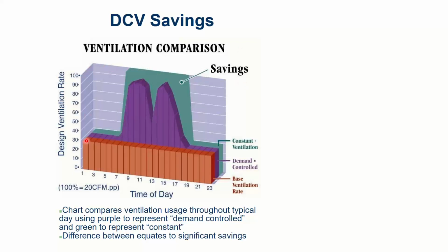But in the unoccupied hours, the damper goes open when I turn the heating and cooling on, and then all the way closed, and then open, closed, open, closed. And for this building, it averaged out to like 29% or something. So instead of showing this sawtooth pattern on the graph, they kind of just averaged it right here. In reality, if the building's unoccupied, you should be shutting your damper. But a lot of buildings don't actually do that, so you get this effect. In any case, this building went occupied at 7 a.m., looks like, all right?